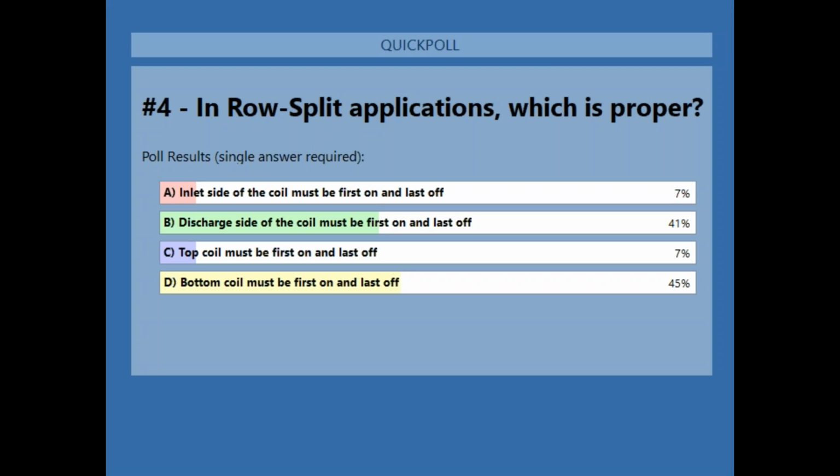All right. So moving on to the discharge line, another vapor line. So discharge line sizing and the effects of it. If we undersize, again, it's going to reduce system capacity. It'll create higher discharge pressure and higher compression ratio, which is a really tough one on the compressors.